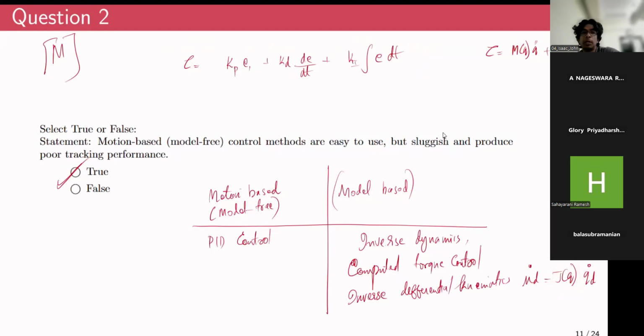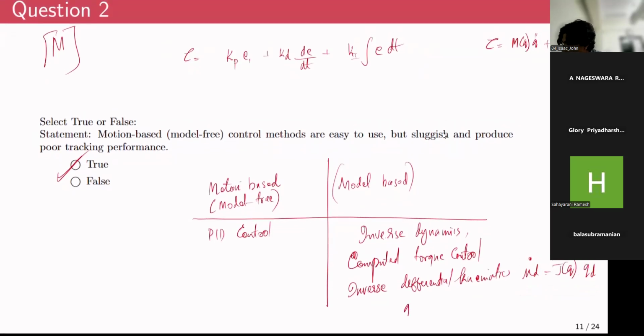When the Jacobian matrix is close to a singularity, in order for your robot to achieve a specific velocity, since it is nearer to the singularity, your q desired dot will also be very high. This q desired dot is considered your input. So depending upon the nature of this Jacobian matrix, your control input would be immediately scaled up. Rather, this q desired dot would be your control input to your motors. This would be J of q inverse times mu desired dot.